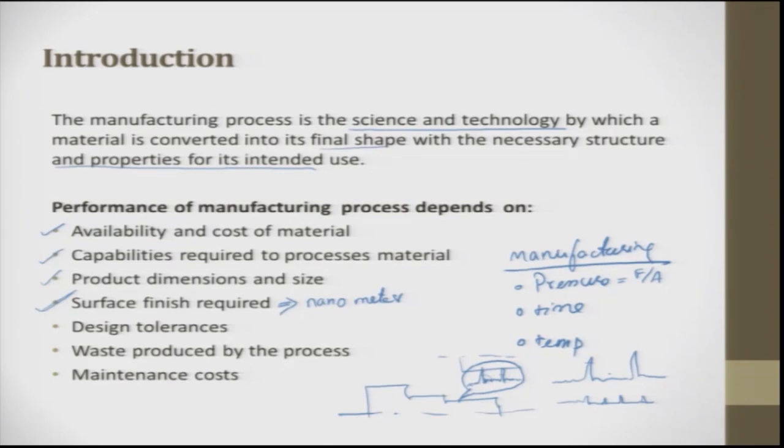So, people talk about surface, and the interesting part is people also talk about textured surface for various applications. In surface finish, please do keep in mind that you can have two different signatures having the same roughness value. It is possible. Two different surfaces can have the same roughness value. So, you have to look at the figure, correlate it with the magnitude, and then decide what is to be done. This is very important.